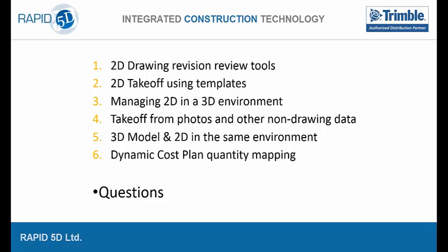Someone here has mentioned file formats in Vico Office. Yep, so I mentioned for the 2D it's PDF, so any type of PDF, and line-based PDF is vectorized, so I can pick those snap points. We can also bring in terms of 3D, IFC, which is your standard construction format. We can also go direct from Revit, ArchiCAD, Sketchup, and Tekla as well, which is another Trimble software.